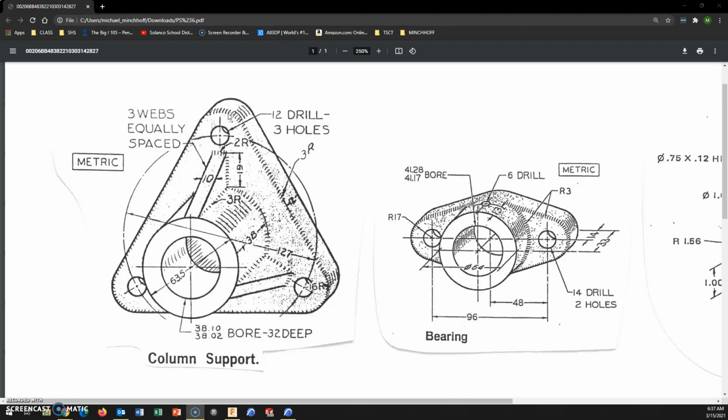So one option is to then use the offset tool. If I make an equilateral triangle for the distance between each of these, I could then offset it equal distance away. For the ribs, if we create a plane down the middle, we can create one rib, and then we can use circular pattern.